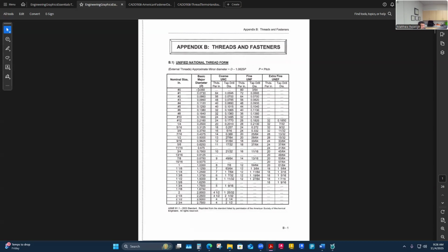It's actually very small, less than a 16th major diameter. A 16th would be 0.0625, so this is a very small fastener, like a 16th of an inch. I think of almost like your glasses type screws. A number 0 is very small. In fact, it's so small that we don't even have coarse thread options in this diameter. There's only one type of thread I can buy in this particular size of fastener, and it's a fine thread.